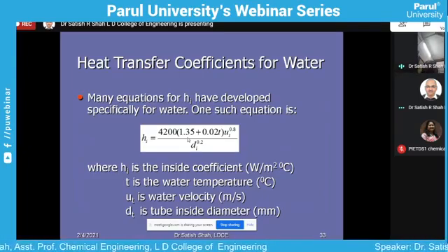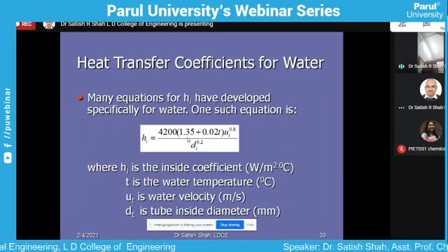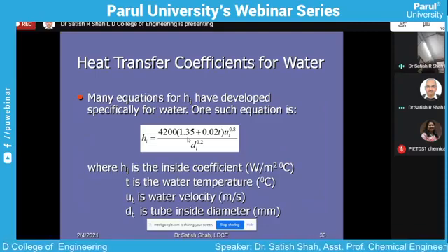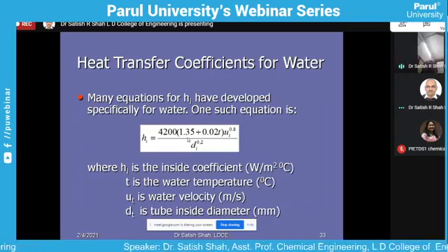I will give you one example. Suppose I have a tube body of 19.05 mm and my tube gauge is 16 BWG. It means my thickness is 1.65 mm. So I can find out tube ID, that is equal to 19.05 minus 2 times 1.65. All right. So that will tell me the value of the ID of the tube.